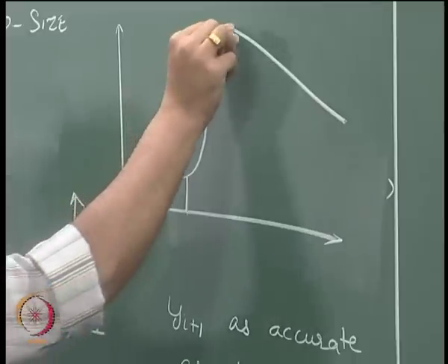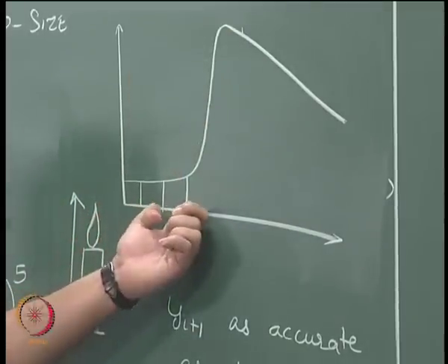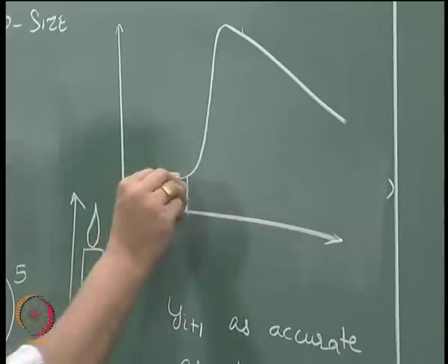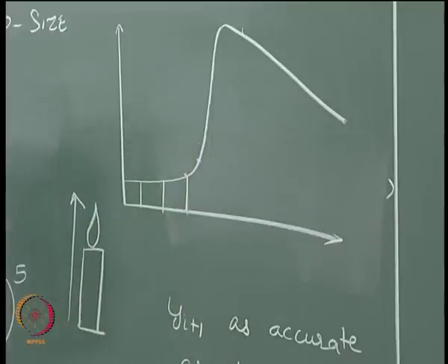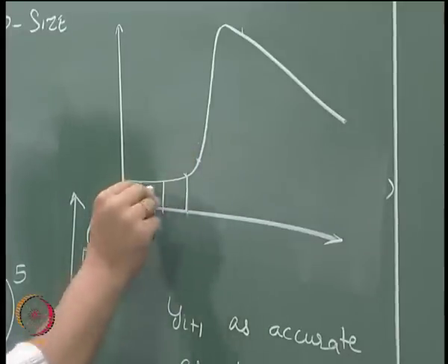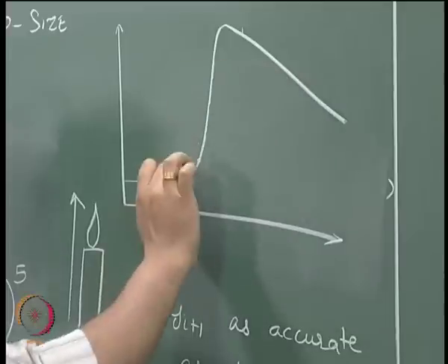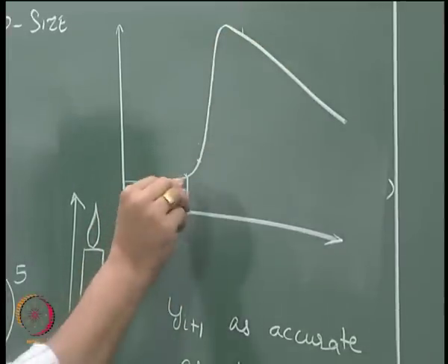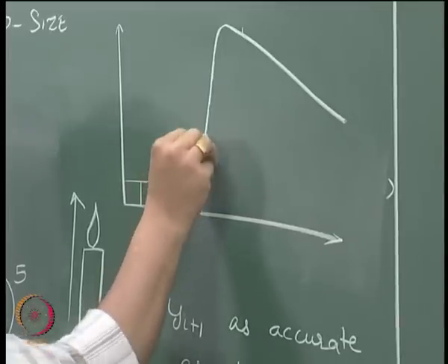Now a lot is happening in this particular region, so things are changing quite rapidly. The slope at this point is drastically different than the slope at this point. So if we kept using the same large step sizes in this region also, we would miss the overall physical characteristics that we see over here. As a result, the adaptive step sizing is going to take multiple steps in this particular region.